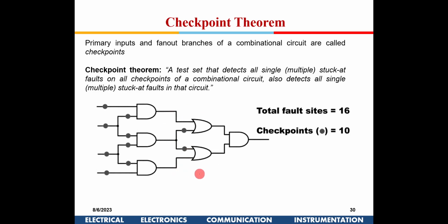As per this theorem, in case there is any branching or any primary input, only those points we have to check. Yes. But if the output gets stuck, suppose I take the example from gate one, if the output gets stuck here, then how are we going to check that? No, it says if you do this, it will take care of that. The fault equivalence or fault dominance will cover it. One of them will cover it, so this test will cover that particular scenario. Yes. Oh, okay. Thank you.